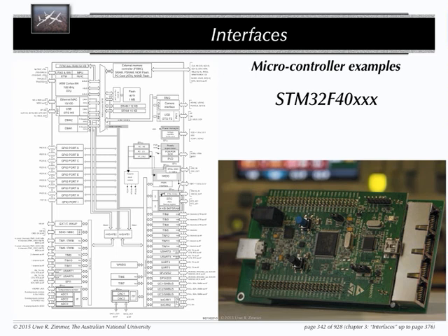You have the USARTs there, lots of timers, I think 12 all up, no, 14 timers you have all up. They're all different, they're all specialized for different purposes. Yes, there are some groups, usually coming in groups of 2 and 4, which can be used in an exchangeable way, but most of these timers can do quite different things as well.